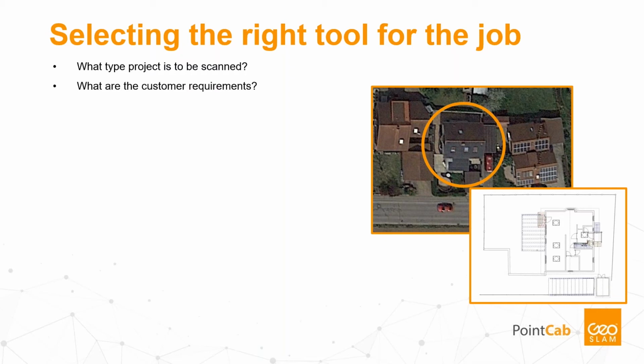What are the customer requirements? Those can often range from the capture time, as the access to the site might be limited, through density, accuracy, or georeferencing. This is also why we will show how to process and merge a combination of mobile and terrestrial scans. What do we want to deliver? We will look at creating floor plans later on in Draw and further utilizing Draw plugin for Revit models.